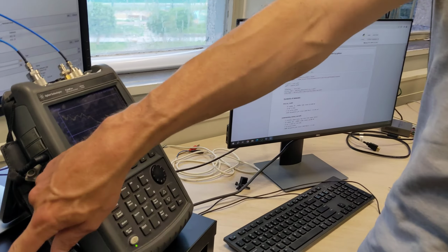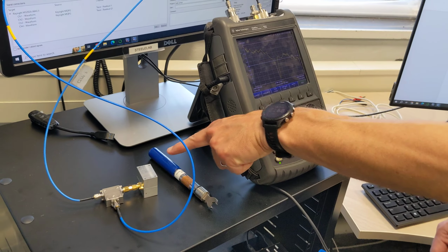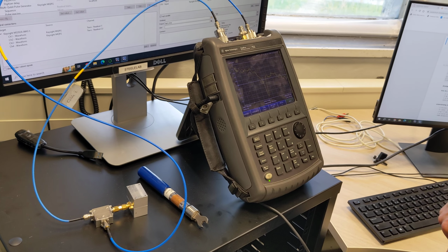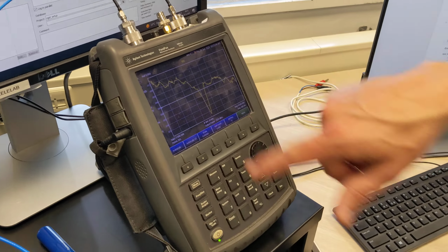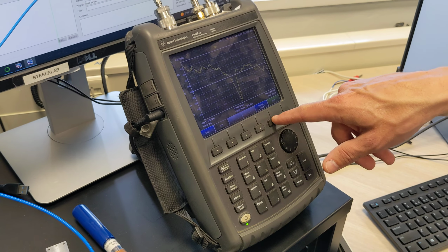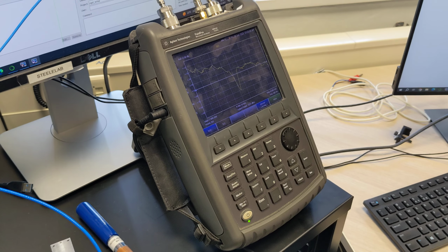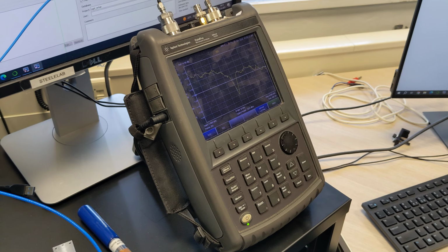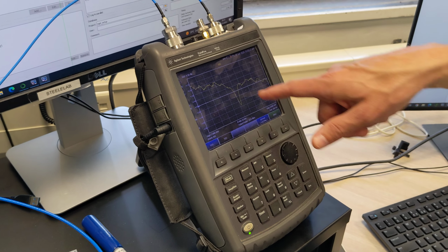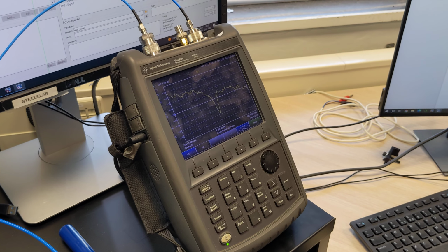We are looking at the S21 of a room temperature 3D cavity through a circulator on the network analyzer. The network analyzer cavity is around 3.5 gigahertz. So let's go to what people usually do. The buttons people usually push are first log mag. There's a little blip, and you're going to trust me, that is the cavity. It's actually overcoupled, so the dip in dB is very small.